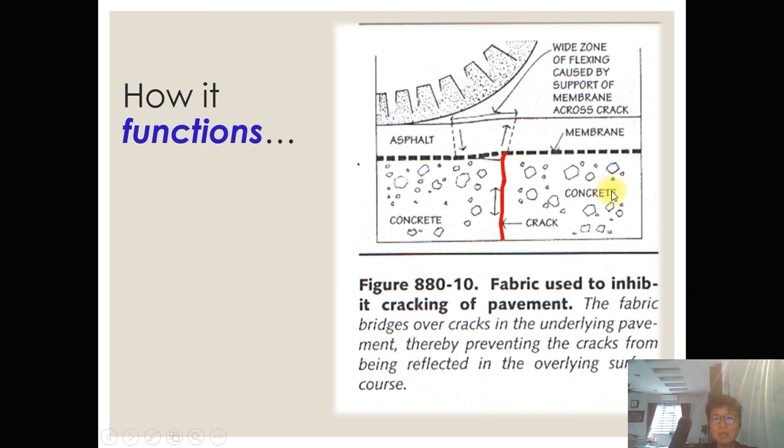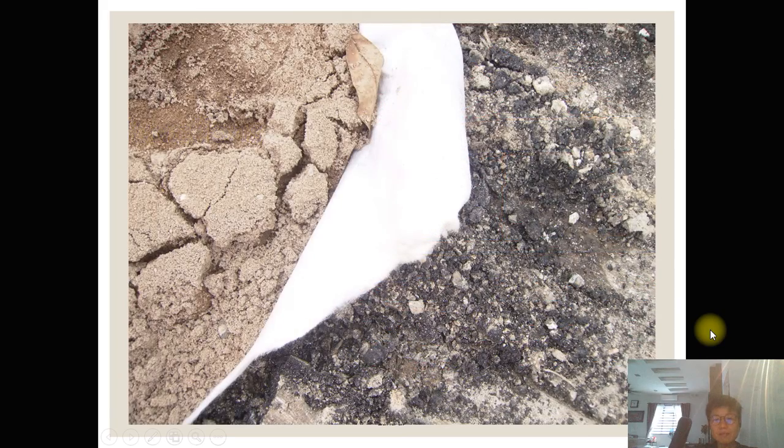Okay, if you look carefully, this is a road that is actually a rigid pavement, concrete, but at the top they want to make driving over it comfortable. They lay a thin layer of asphalt. Asphalt is bitumen, and they are very smart to put in a separator to avoid this from happening. And this probably is a low cost construction, so maybe the joints are not quite in place, or the joints are put further apart, and then the cracks can take place. Like that.